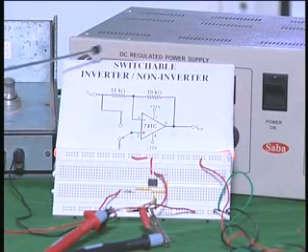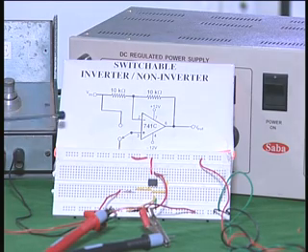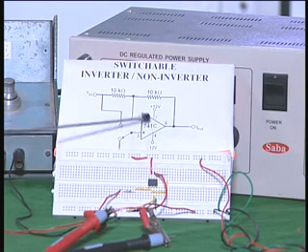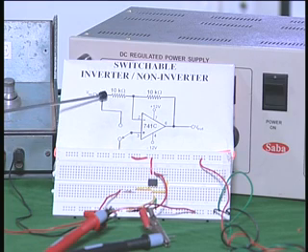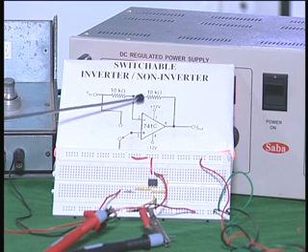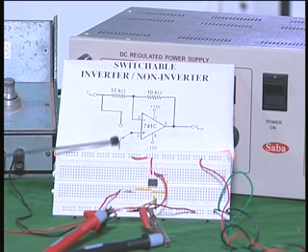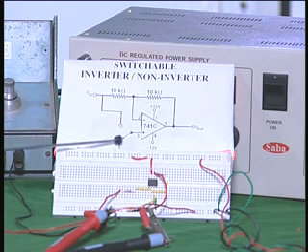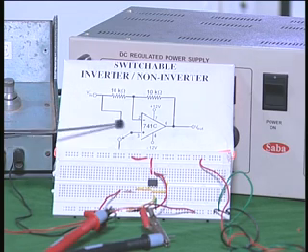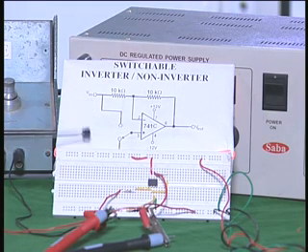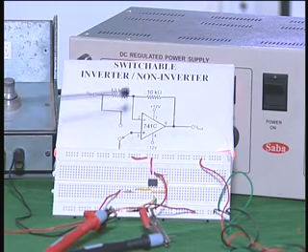I want you to see the circuit here. It is the same as the one which I showed you just a couple of minutes ago. You can see there is an operational amplifier 741 at the center. There are 2 resistors which are called R and R in our circuit. This is 10 kilo ohms, this is also 10 kilo ohms, and you see here that the non-inverting input can be either connected to the ground or connected to the V in input by using this switch. Instead of the switch, I am going to use a wire which can be connected either to this end or this end. That is the only difference. The same circuit is wired here.